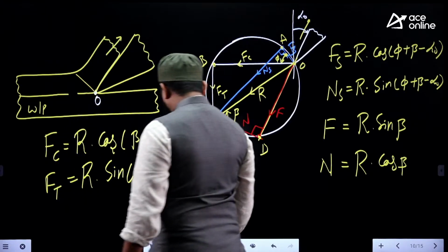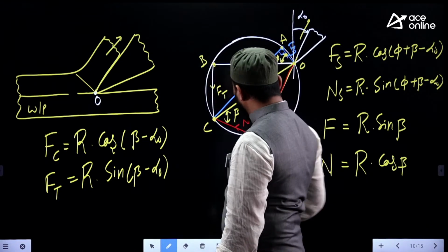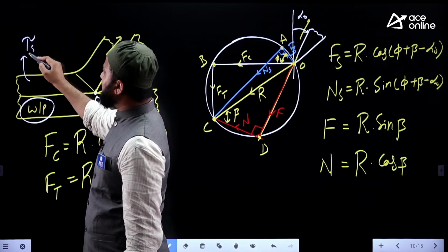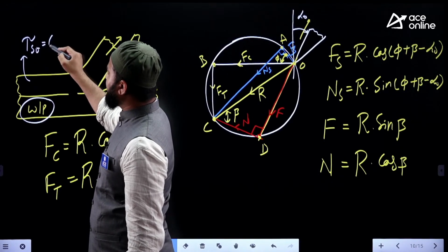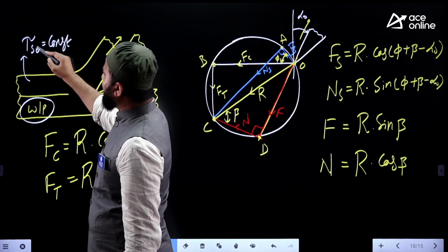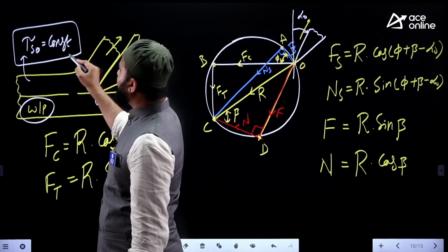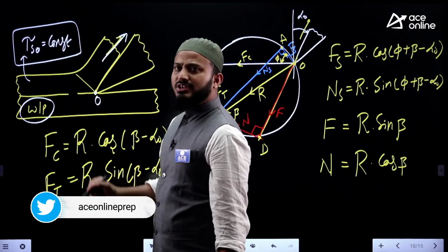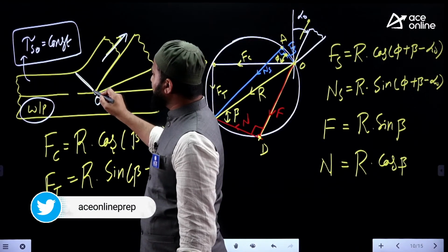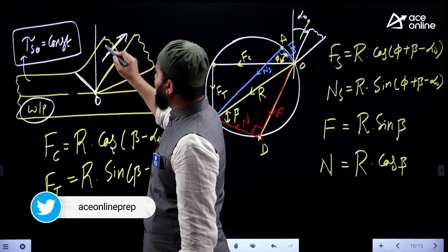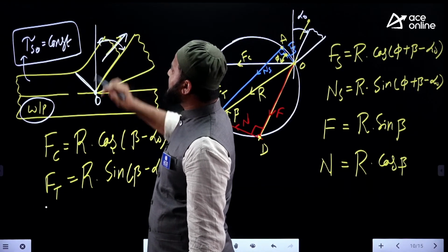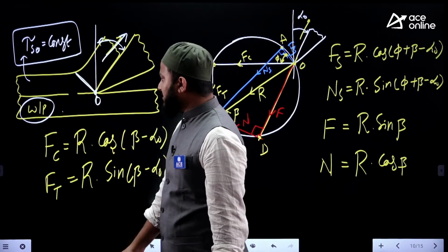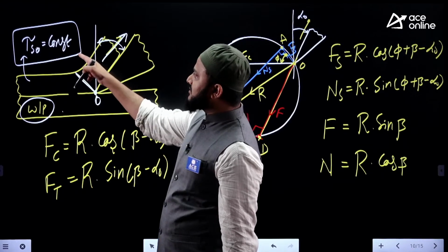Whereas the selected workpiece material we always consider as rigid, isotropic, having a shear strength tau s. The dynamic shear strength of the workpiece material is also a constant. Practically not possible, but we assume that the workpiece has a constant dynamic shear strength, and because of that assumption we get continuous chip formation without any built-up edge whenever the tool is engaged. But practically, if you notice, various behaviors of the chip we observe. But to make analysis simpler, we assume the workpiece is a rigid ideal plastic material where the shear strength is constant.